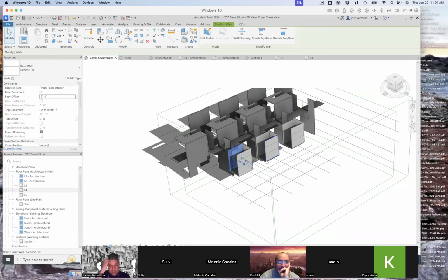So that's the key thing here, thinking about a hierarchy of decision making, right? Establishing a grid as an ordering system, working with it rather than against it, placing in some basic modules, making sure that you figure out circulation. In this case, I would have probably a couple places where I can go up and down, and it's pretty clear I have some lateral circulation spine moving from east to west in my case. Doesn't have to be that way, right? But thinking about how you do that, how you begin to give order to things in big ways, the big moves first?